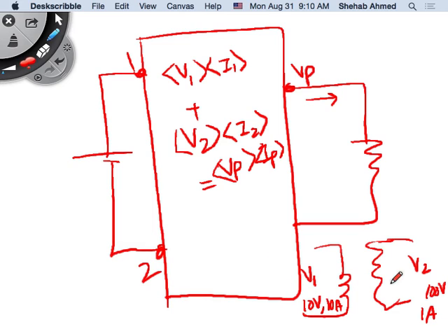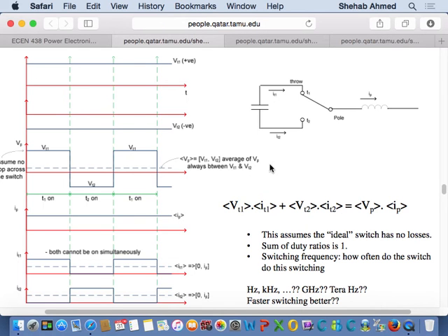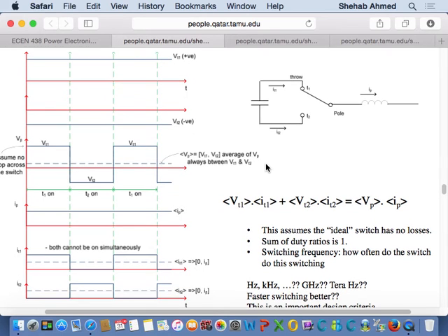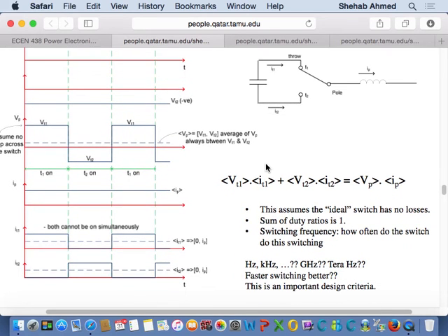So 100 watts is equal to 100 watts, assuming the transformer is lossless, and it's the same thing with a power converter, right? The power flowing from this node into this box is equal to the power consumed by the load, right? So it's a constant power transfer device, yeah. So we will get into the waveforms later. I just wanted to make sure that's clear.